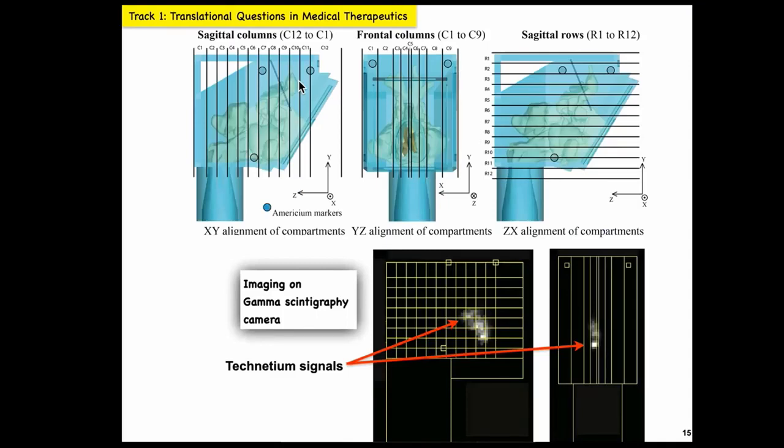initially, based on the radio density on those images, we can create some kind of threshold to get the bulk of the air space into the solid model. But after that, my knowledge of anatomy is not that great, so I work with the clinicians in the team, and they help us in improving the anatomic realism of those geometries. They would go through each of those 250 or 300 such slices and correct the pixels on those scans. And that's how we build the geometry. So we get feedback from the physicians that the geometries that we come up with are clinically realistic. So that answers your first question.